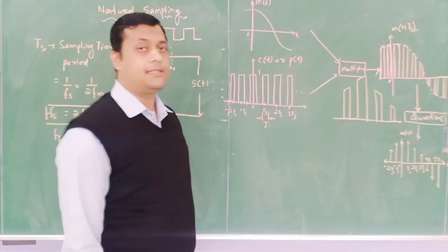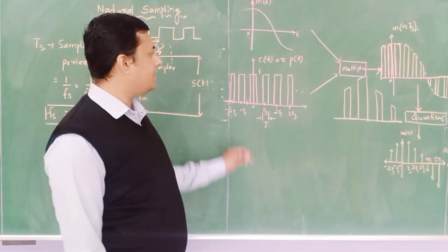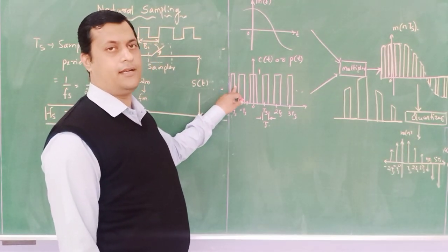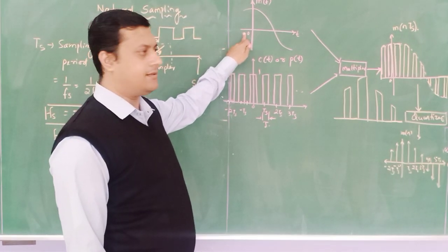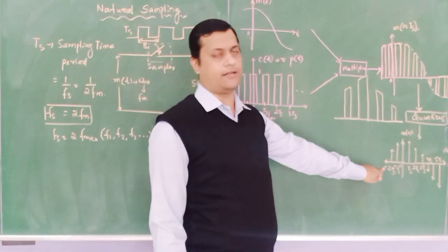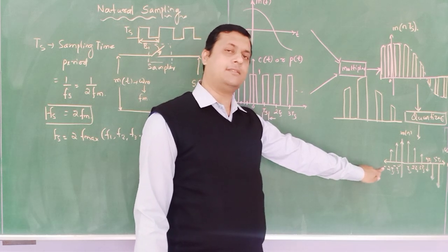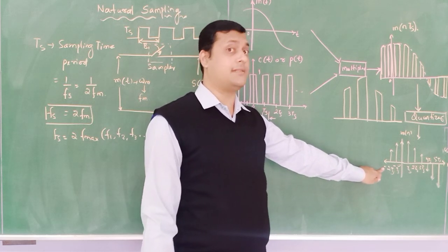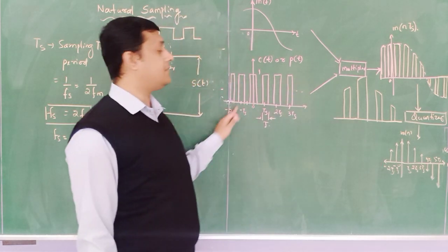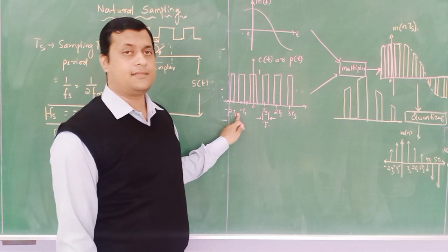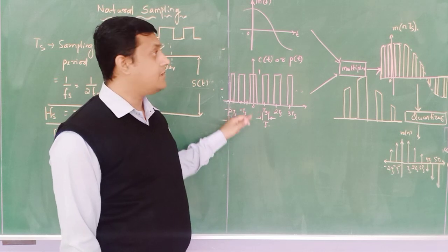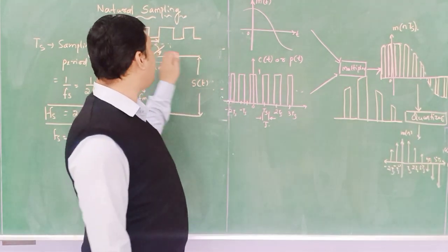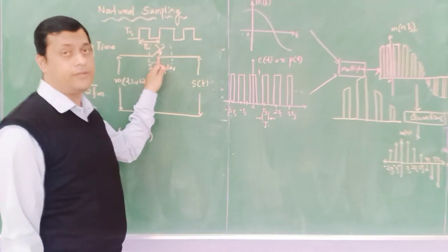So when we use instantaneous sampling, there is an impulse train multiplied with your modulating signal, or your continuous signal, and we directly get the discrete values. But in natural sampling and flat top sampling, it doesn't happen, because here we have considered pulses. The pulse is nothing but a rectangular function. So this pulse train we have used as a particular switch condition.